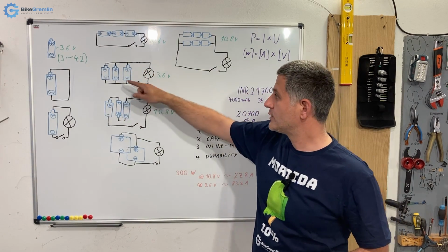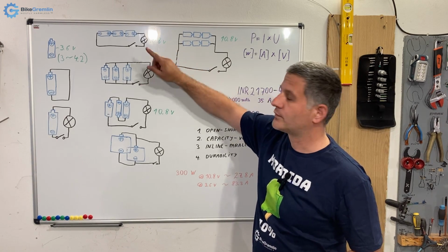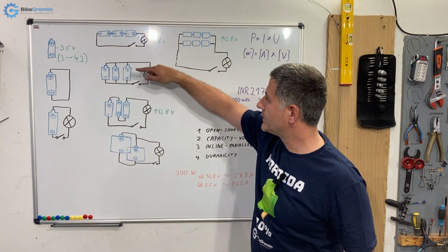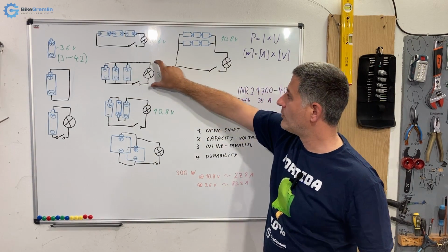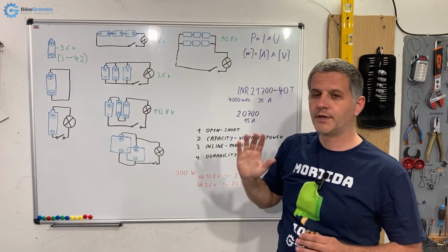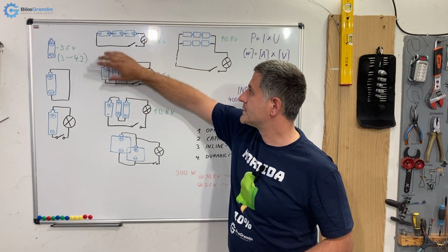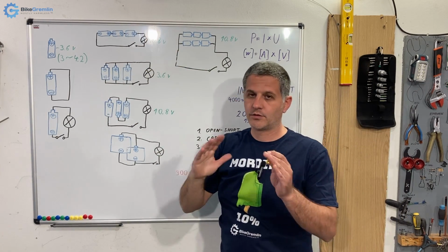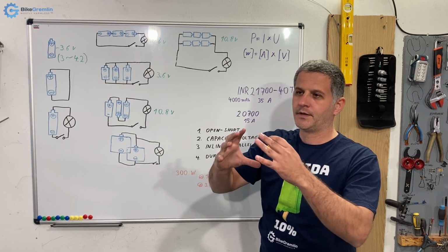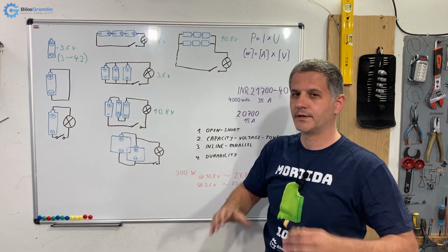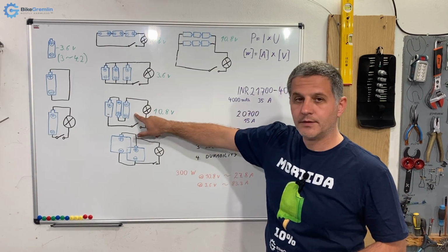triple the capacity, because when current flows in this circuit, if we have, let's say, 3 amperes flowing through the circuit, it will be taking 1 ampere from each battery, because they are all connected in parallel. You can imagine this, visualize it as water pipes, their thickness and connecting them. That's for me easiest to understand. Voltage could be regarded as pressure and current as the thickness of the flow, how much water is flowing at any certain time.